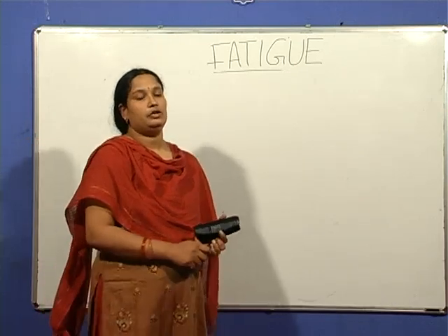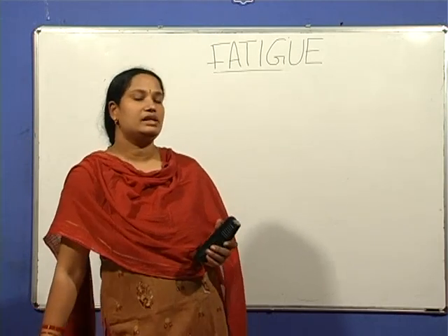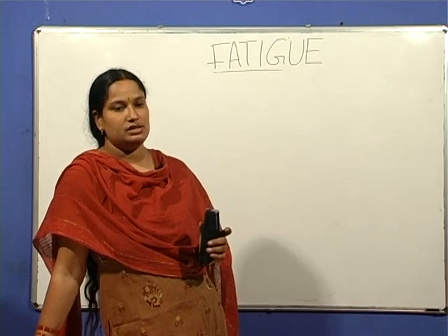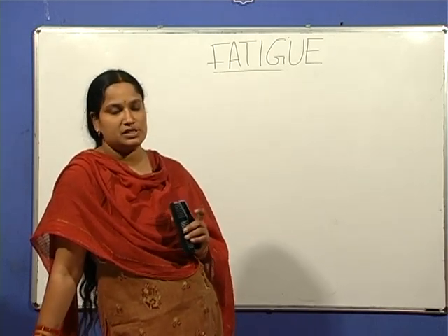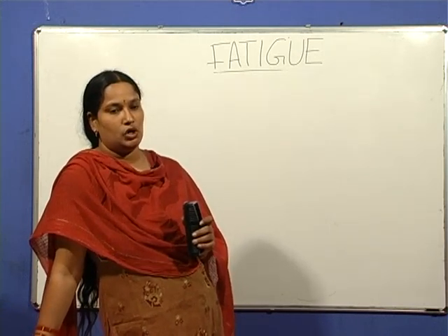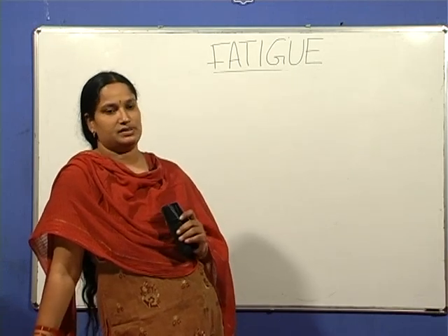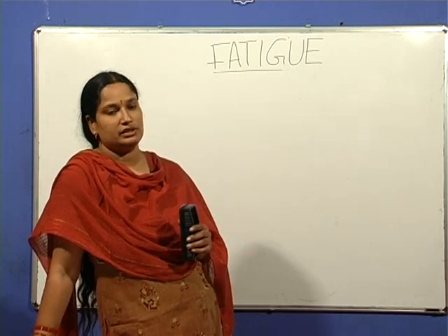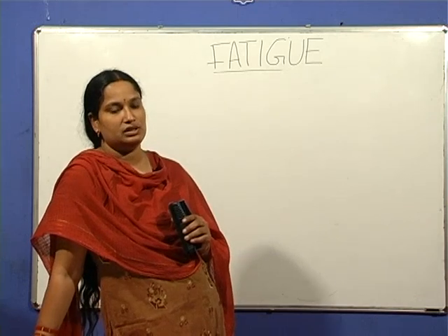Now, fatigue crack nucleation and growth. Fatigue cracks generally initiate at the free surface. If there are any notches present on the surface, roughness of the surface, or discontinuities of the surface, all these lead to the initiation of a crack at the surface. Fatigue cracks can also generate in the interior if there are certain discontinuities, porosity, etc.